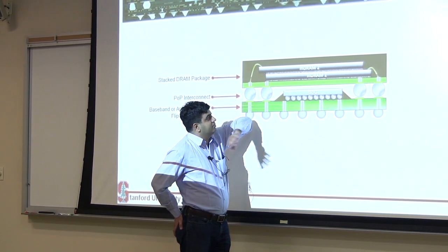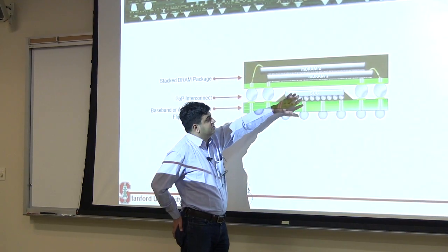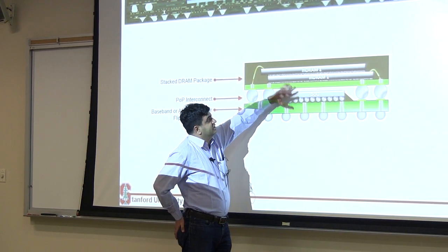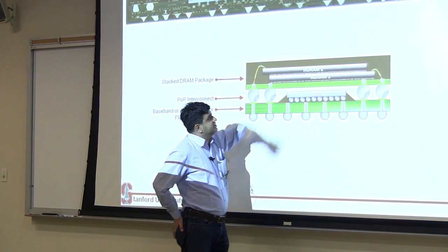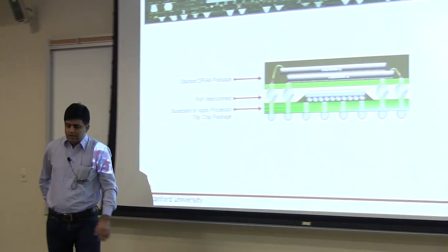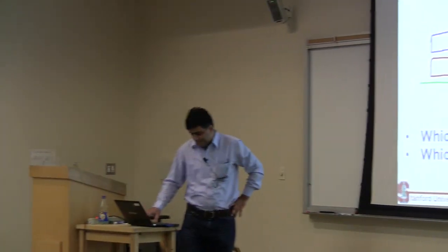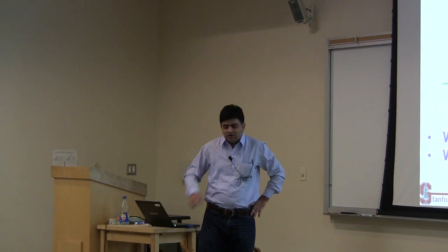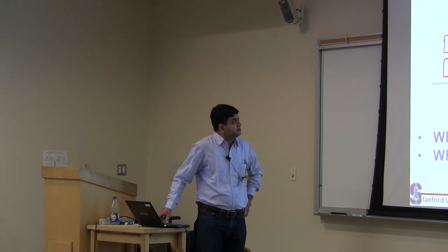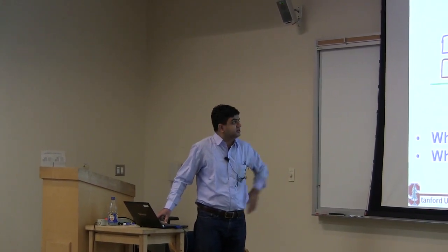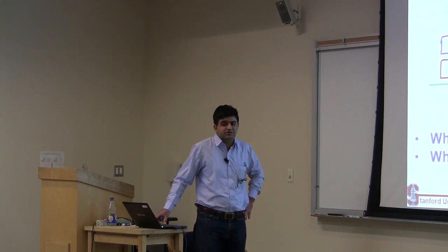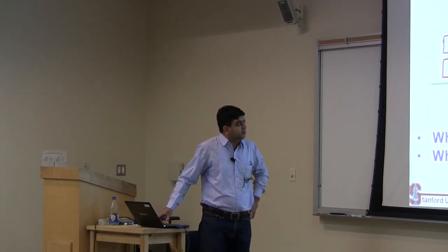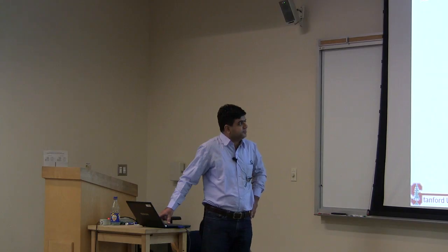But it's a really shabby implementation from a thermal management perspective, because this will heat up, and then in turn that will heat up your DRAM. If you know a better implementation, you can tout it out. But essentially there's not much you can do there. Only two chips, and you can only place them two ways.